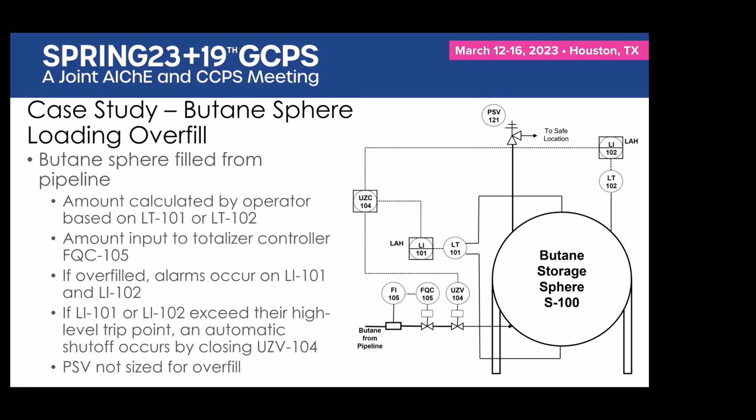And that allows you to do your LOPA and your SIL verification independent of each other because they are physically and functionally independent. When your LOPA and your SIS share components, you can't analyze the risk separately anymore. That's why that same fault tree that you would do for your SIL verification resides inside your overall risk analysis of the plant.